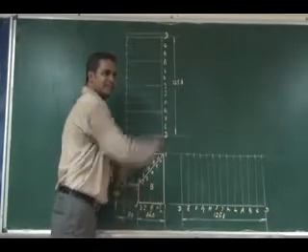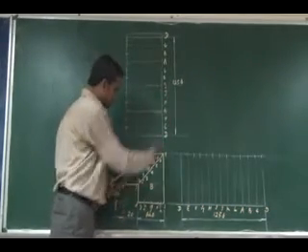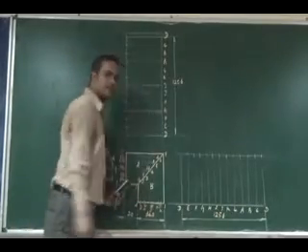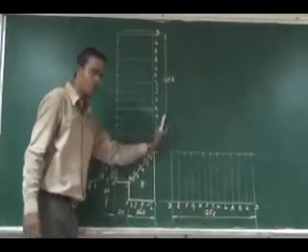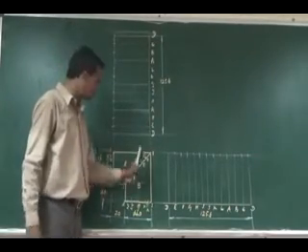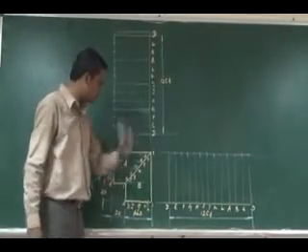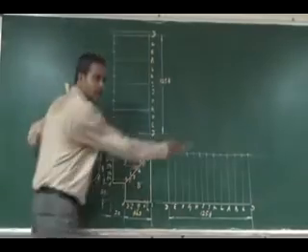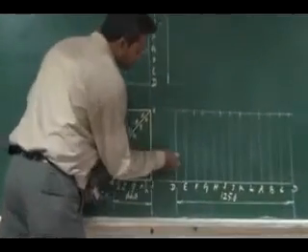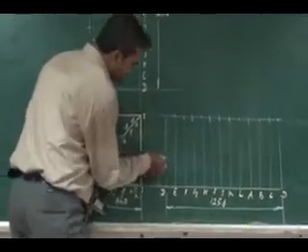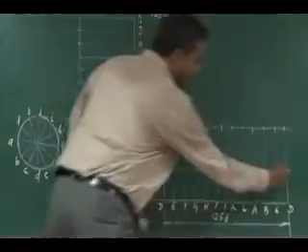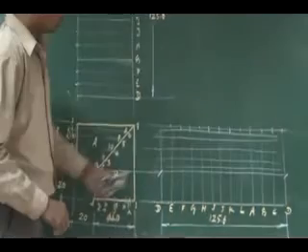Once you have notated that, the cutting points can be represented as usual. The intersection line is nothing but my cutting point. The intersection of these two lines represents my cutting point. I can mark 12 cutting points since it passes through all 12 generators. These cutting points have to be marked by parallelly projecting, similar to your previous problem. So this is my cutting point 1.